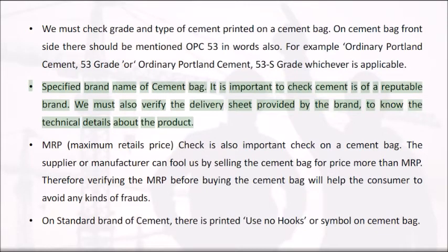Check the brand name on the cement bag. It is important to check that the cement is of a reputable brand. We must also verify the delivery sheet provided by the brand, to know the technical details about the product.